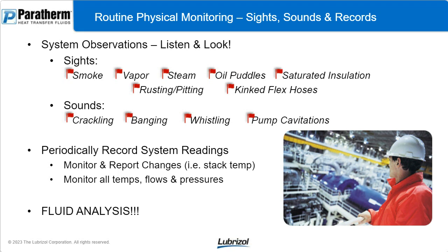They're going to cause a lot of problems down the road as well. Listen to the system. Is the expansion tank crackling? Is there banging in the system? Is that vapor, or anything else trying to get released from the system itself? Listen for whistling, any high-pitched sounds, pump cavitations. Anything that's outside of the norm is a red flag.